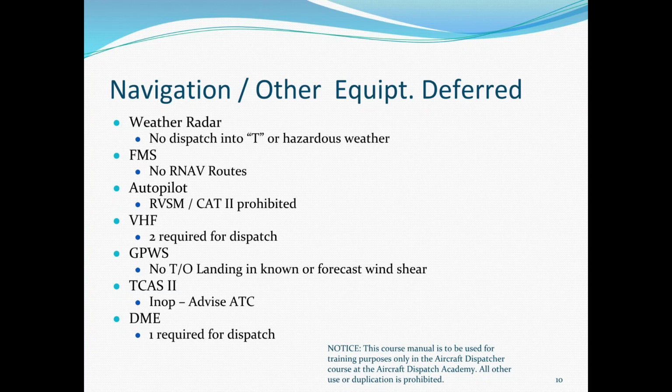If you guys remember the VOR receiver, the ADF or whatever, the instrument has two sets of needles. So when it has the satellite and the VOR navigation, one set of needles, I believe the satellite navigation needles are red, and the ground-based needles are green.